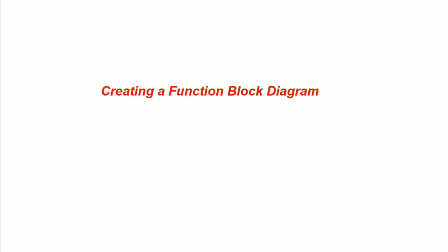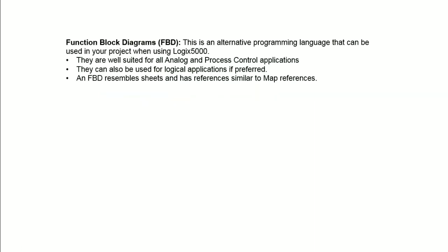I'm now going to show you how to create a function block diagram. A function block diagram is an alternative language you can use when you are working with Logix or Studio 5000. It's perfect for analog and process control applications, but it can also be used for other applications, including logical, and it is extremely flexible and versatile.